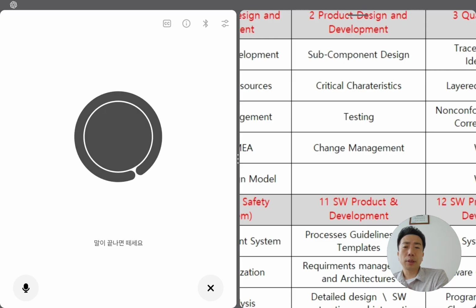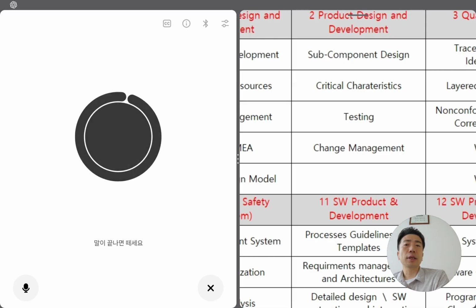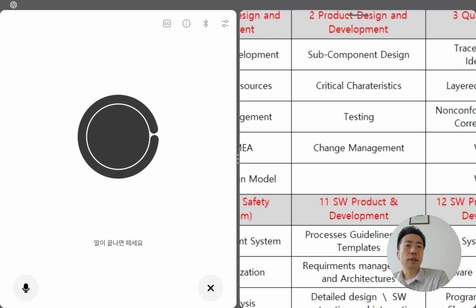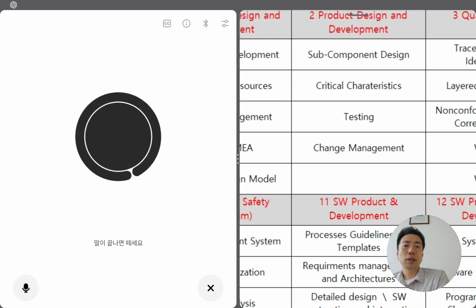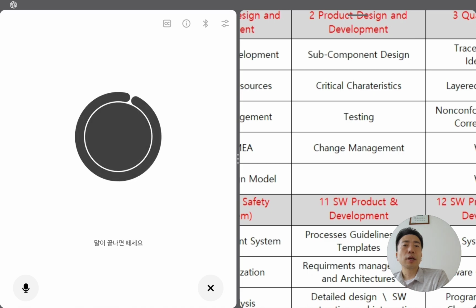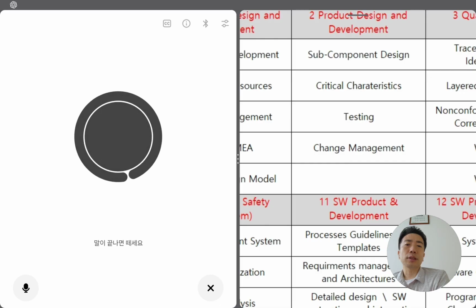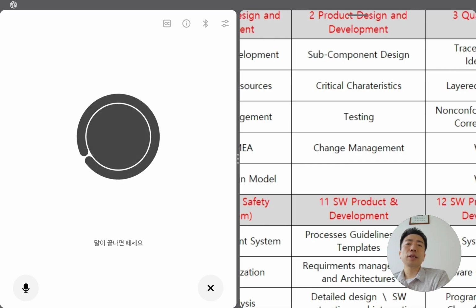Listen. I'd like to repeat your polished version one more time. This is the supplier's ideal answer, OEM versus EMS case. In OEM projects, our engineering team, including design and production engineering, defines critical characteristics based on risk analysis and DFMEA results. In EMS projects, our customer defines the critical characteristics and we follow their specifications.